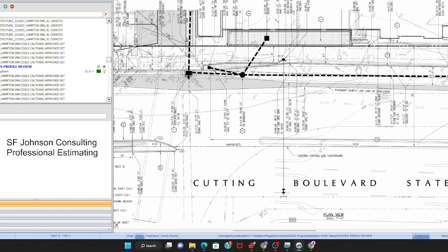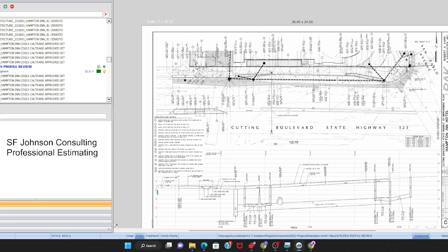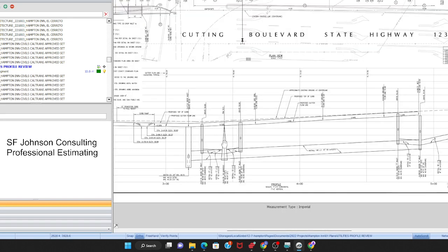Then how do you determine your cubic yards of backfill dirt? Well, the cubic yards of dirt you took out minus the area that the pipe takes in cubic yards, basically, if you really want to get that deep with it. And you should, because you need to determine from the cut material if you have enough for the fill material, considering all the other things you have to do. But if you are digging out basins, way down in here, chances are you have enough fill material for after, because you have to fill in where your pipes are, and all this is dirt